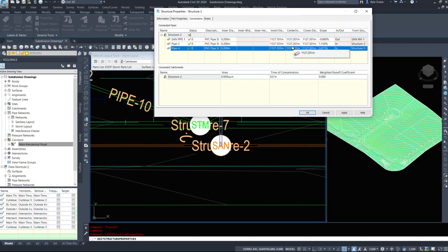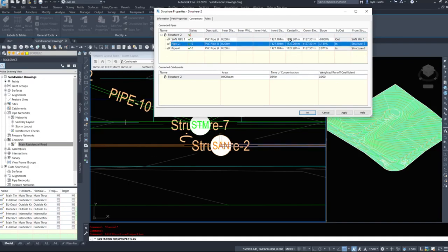So the way we handle this, where I live in Calgary here, is we have what's called a manhole drop. So the pipe coming in, depending on if it's 0 degrees, if it's straight in, if it's between 0 or 1 and 90, it'll come in at a different elevation. If it's between 90 and 180, it will come in at a different elevation. So all that means is this pipe is straight in, straight out. So the pipe out to the right will be 0.03 meters higher.